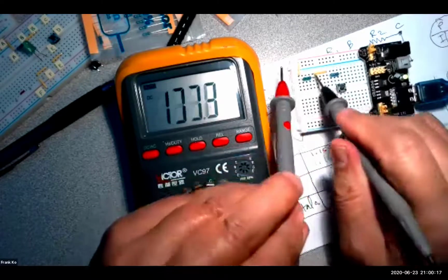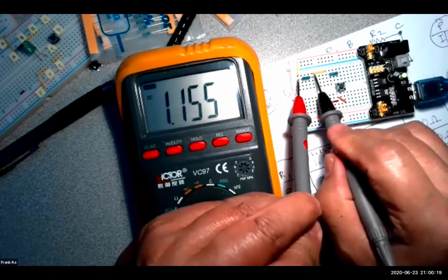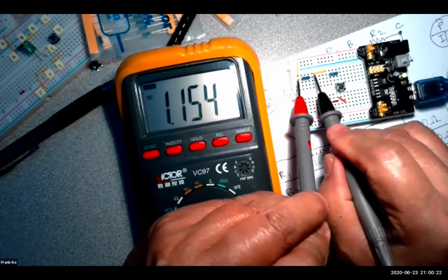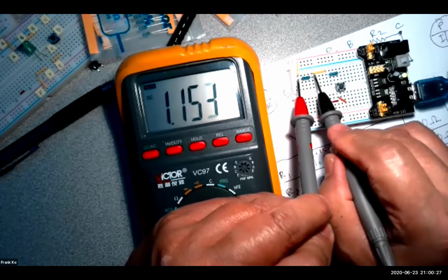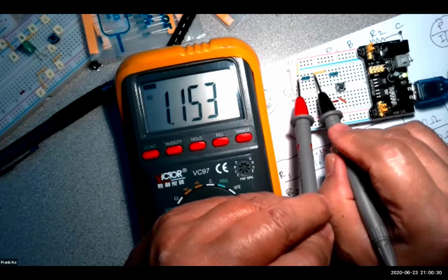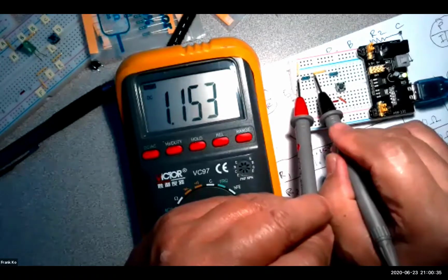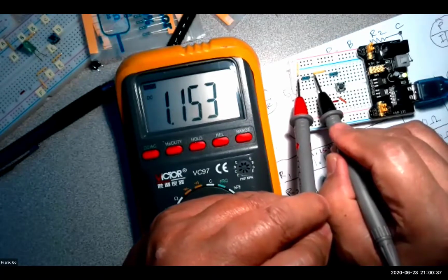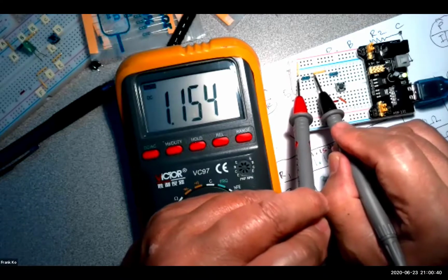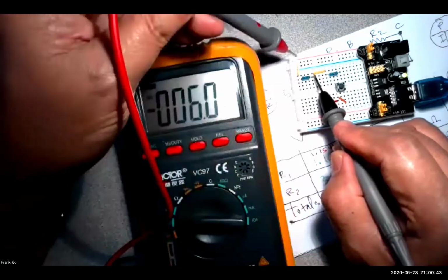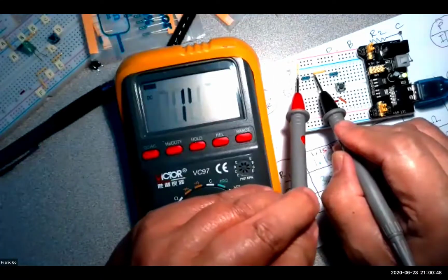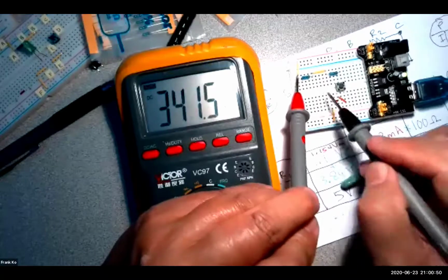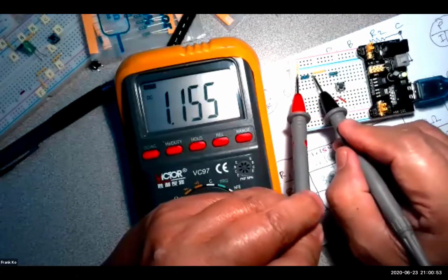Now, if I go here to here, and I just touch here to here, I will have my 1.53, 1.54 volts. Now, suppose I switch the polarity of my leads. Right now, the red lead is on the positive side of that resistor, and the black lead is on the negative side of the resistor. Why is the red lead on the positive side? Why is that left side called the positive side of the resistor? Because the left side of R1 is, in fact, connected to the positive rail. So as it's connected to the positive rail, this side of R1 is positive, and the right side is negative.